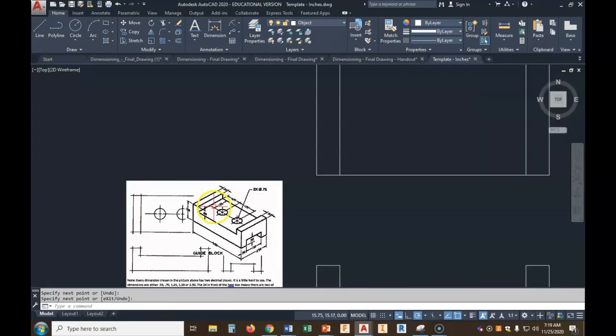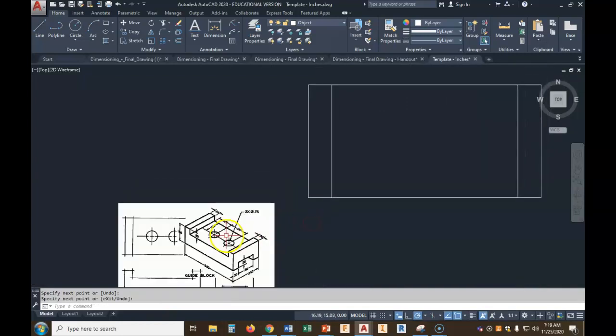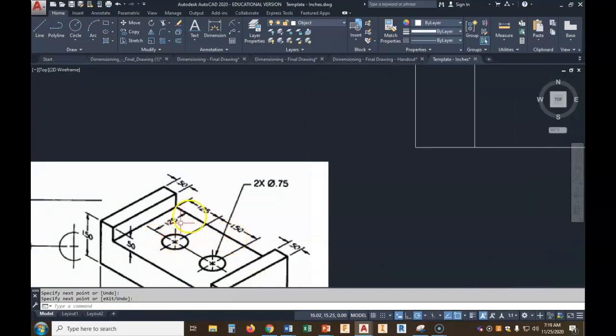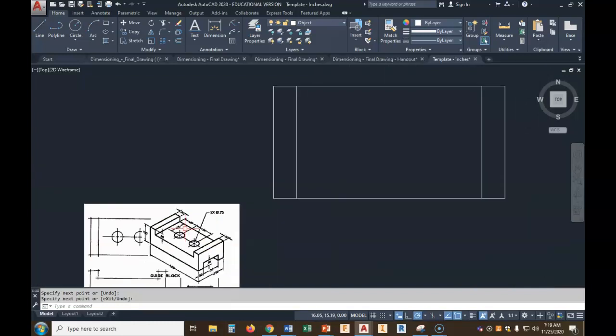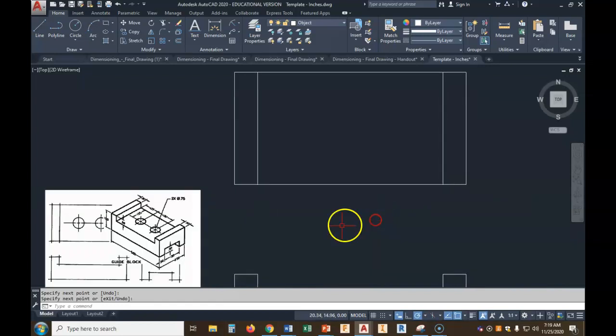Now we can see the holes from the top view, right? Now look what we've got. 1 1/4 in, 1 1/2 between them, and 1 1/4 this way. Okay? So let's go ahead and draw a center line. Now, it's 2.5 deep. This is where you need to get to the point that you're starting to recognize things. 1 1/4 is half of 2.5. That should be one of them things that pops in your mind. So I can work from the midpoint of this line because that's measured from here, okay?